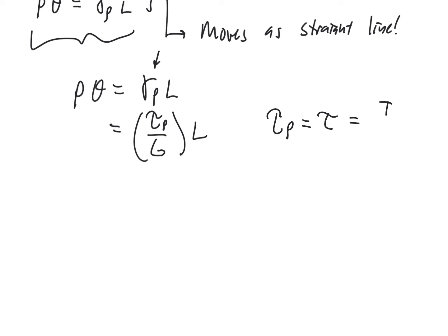So that's going to be the torque multiplied by that radial distance, all divided by J. So we dropped the rho just because we decided, hey, we don't really need that rho. We are going to assume that it's going to be calculated at any one of those arbitrary radii points. So this is going to be T rho over J, that's tau at rho, and then the G comes here.